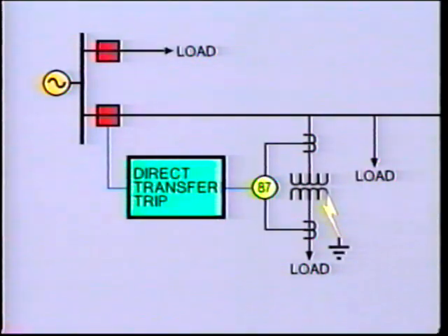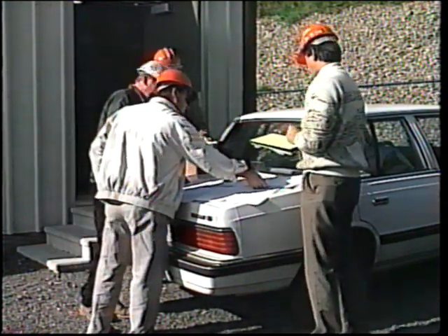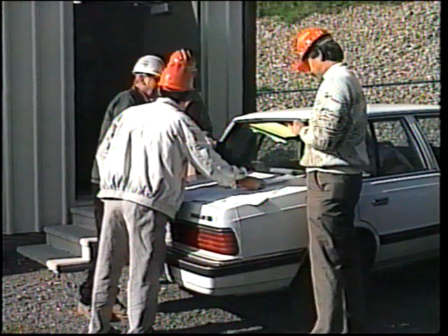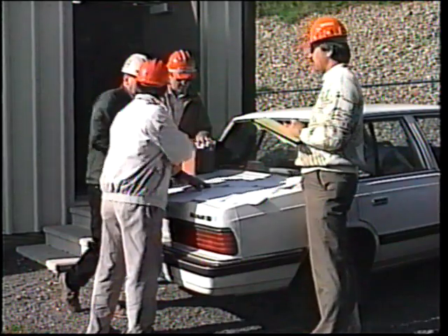Also, during such a fault, it is vital that the various communication channels remain intact so as to permit relaying functions and transfer tripping to take place. We certainly do not want the wire pairs to fail at this time. Obviously, good coordination between the two companies is absolutely vital. One obvious reason is that the telephone company personnel probably do not appreciate all of the problems facing the power engineer, and vice versa. Only by looking at each other's requirements and limitations can satisfactory protection be provided. And this is another good reason for paying attention to this videotape.